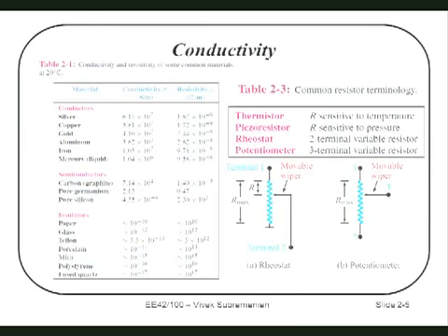Here's what we do. We take this resistor and we put a little probe that can touch at any point. And we bring this out as the wire. So one wire would be this side, and the length of the resistor depends on where we position this probe. So it rotates, and depending on where its position is, it sets how much of the tubular system is actually part of the resistor. And so the way we show that is like this.